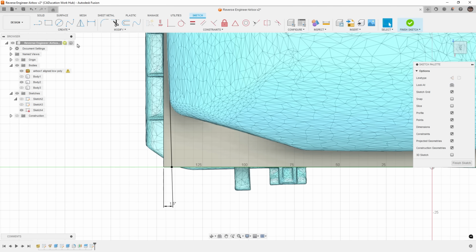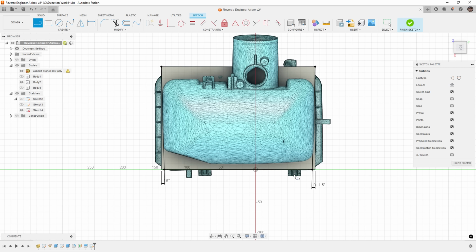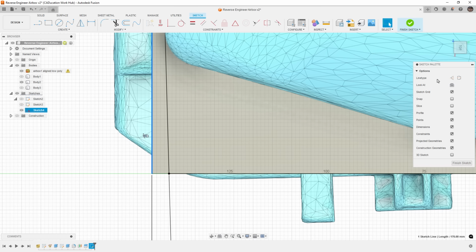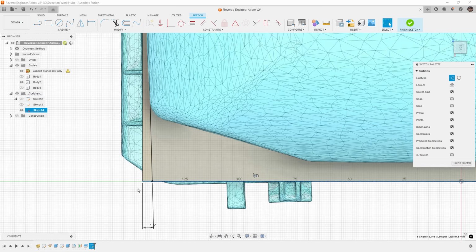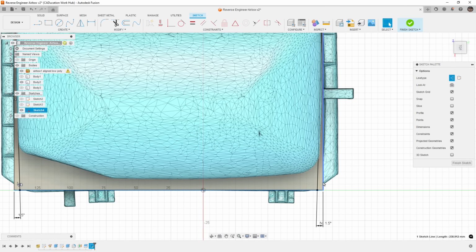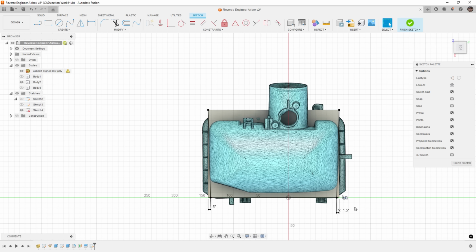and I want to connect that and this. Now, you might be thinking, why did you do that? You don't really need to. In reality, I don't, but I like to convert these to construction. The edges I don't need are the edges that don't have that coincident relationship in the corner. And mainly because sometimes you'll find that profiles can be finicky, especially if you decide to come back and change them. I don't want to give Fusion any other possible scenario other than this one single profile.